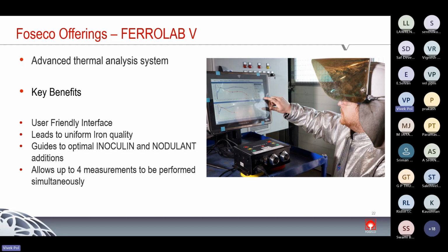With this device we can take 4 samples at a time. It is wireless, and we generally install 2 channels at the pouring section and 2 channels at the melting section, so that at a time we can compare metal quality at furnace level, and when this metal is transferred for pouring, after inoculation addition, how much improvement in metal quality we have achieved.